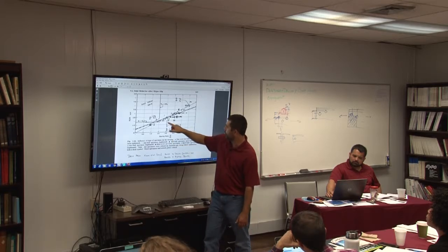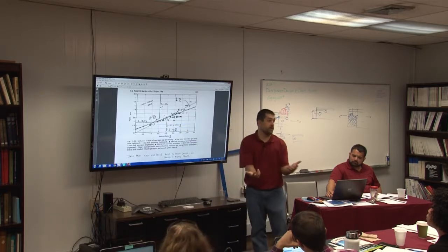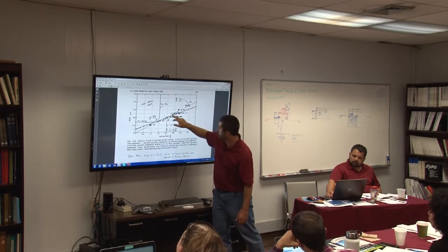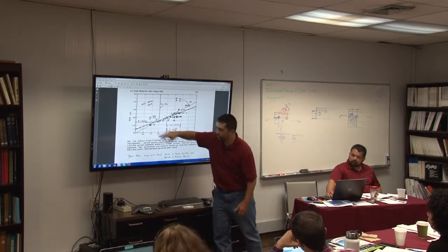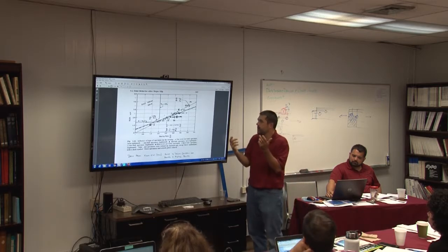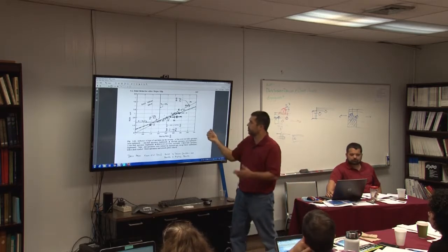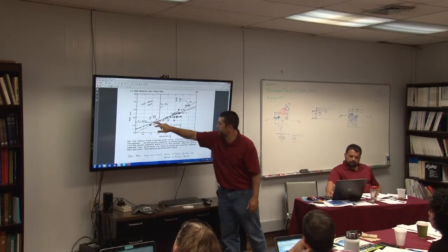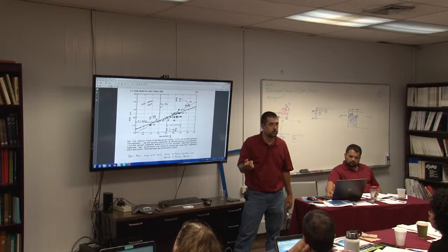The theoretical equation that I derived above using different base principles is basically this dark line. So I can see that theoretical bearing tear out capacity, right? If I specify so that bearing controls over tear out, you find that relationship very well matches the data.